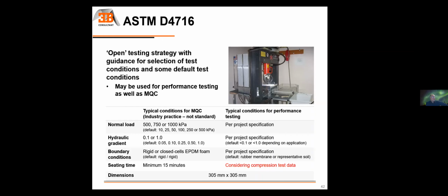The sitting time for the performance test should be selected considering compression test data of the product to be tested. I've been 25 years in this industry, and I noticed that only this week. Because practically everybody is using the same standard sitting times of either 15 minutes or 100 hours.